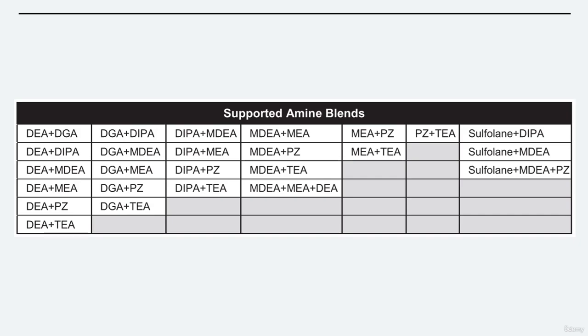These are salt components that are present during the acid gas treating process, but do not need to be explicitly listed by the user when defining components. Heat-stable salts are accounted for by the generated amine reactions available in HYSYS. You will generate and view these salts after you start the simulation.